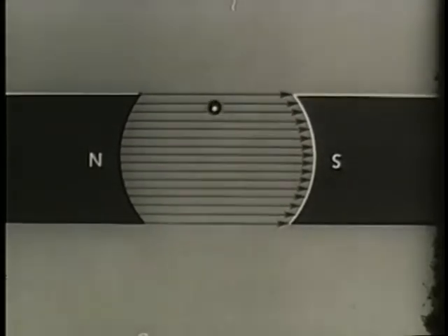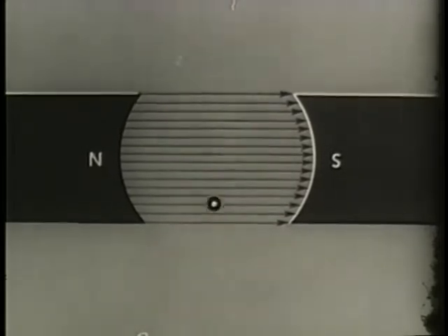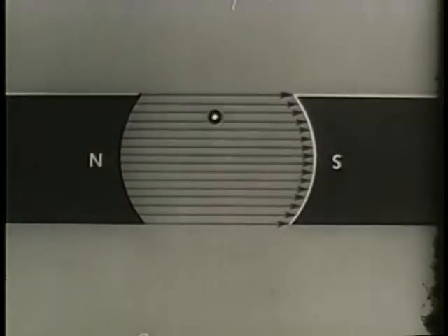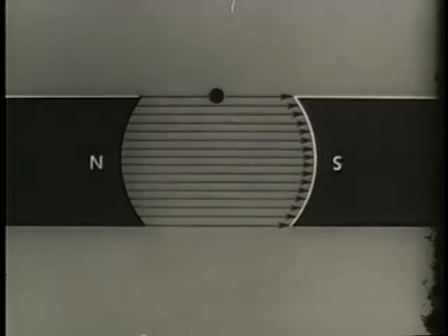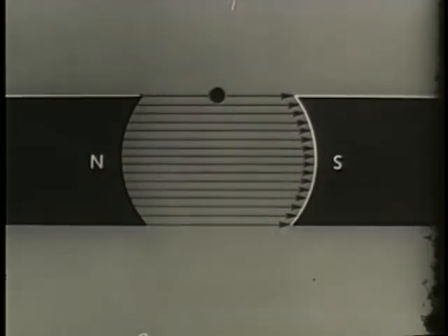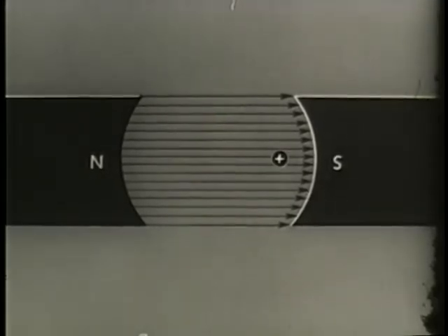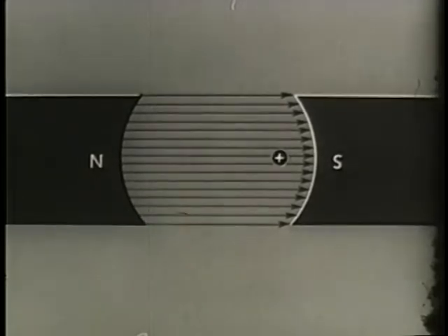But the conductor in an actual machine is not moving in a straight line, but rotating. When the conductor moves in a rotary path, the number of lines cut varies depending on the position of the conductor. At the top of the field, for instance, no lines are being cut and no EMF is generated. As the conductor keeps turning, the number of lines cut increases, so that at a quarter turn or 90 degrees, the maximum number is being cut and maximum EMF is generated.